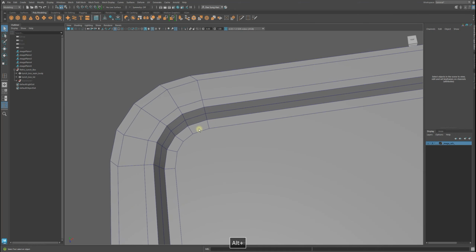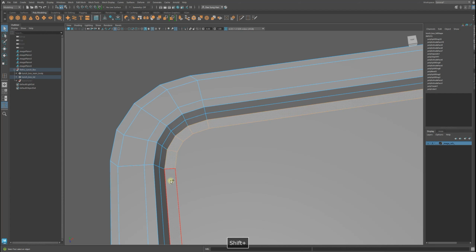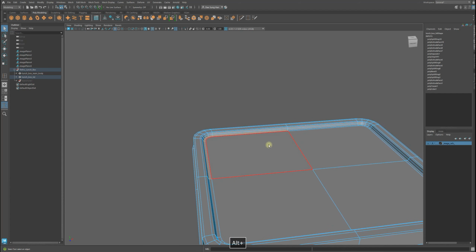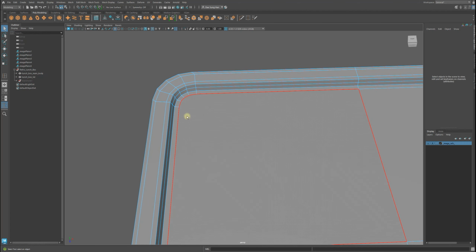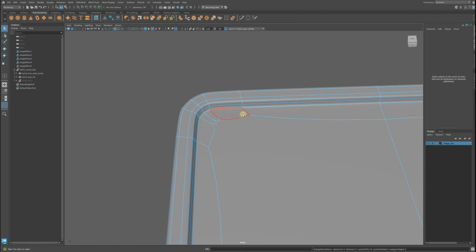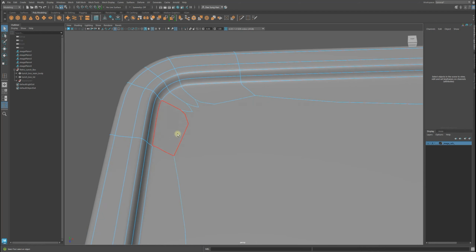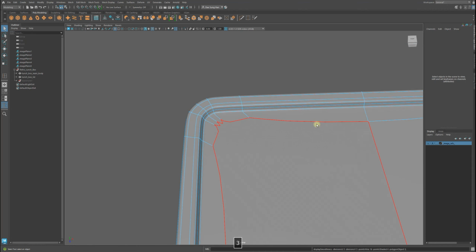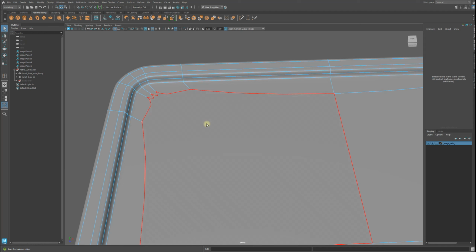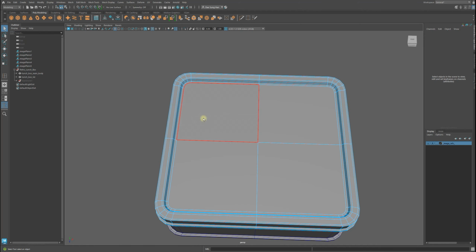So I like this much distance right here, right? This much spacing, because here is where I'm gonna have the UV map to save the real estate, to project and put your illustration. And then when I press 3, ooh, see, this is what we have to watch out for. So we got this distance is correct. Now I need to refine it so that when you UV project, it's not gonna look like this.